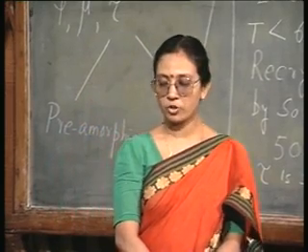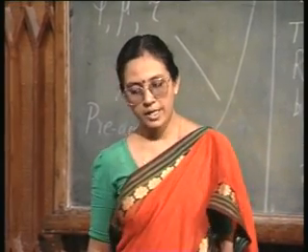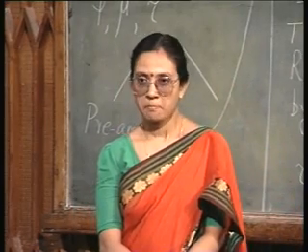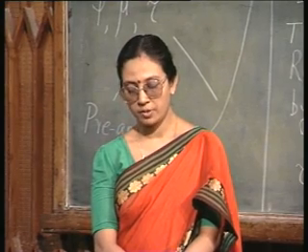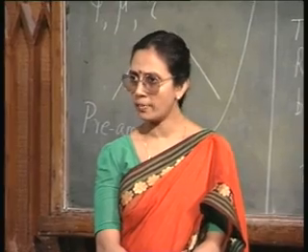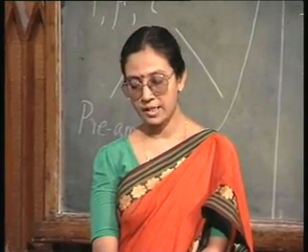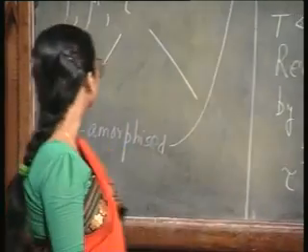In this case, I have a low dose implant, low dose light ion implantation, you have full recovery of all the parameters, conductivity, mobility as well as lifetime by 800 to 950 degrees centigrade.